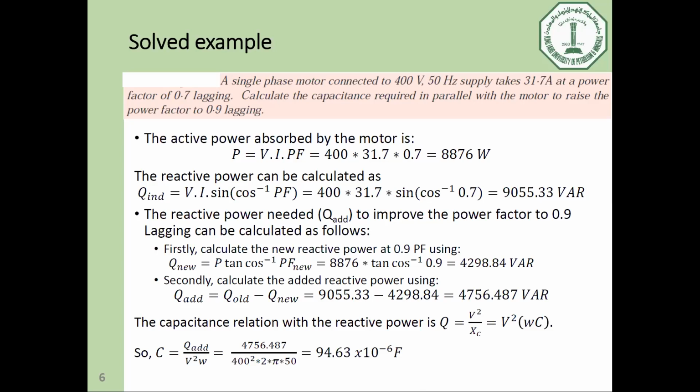Because for instance, we have a certain mechanical load applied to a motor. It's not logical to reduce the mechanical load in order to improve the power factor. Power factor is a matter of power quality. However, you have a target, which is to operate the mechanical load. So in order to improve the power factor, you cannot remove the load.